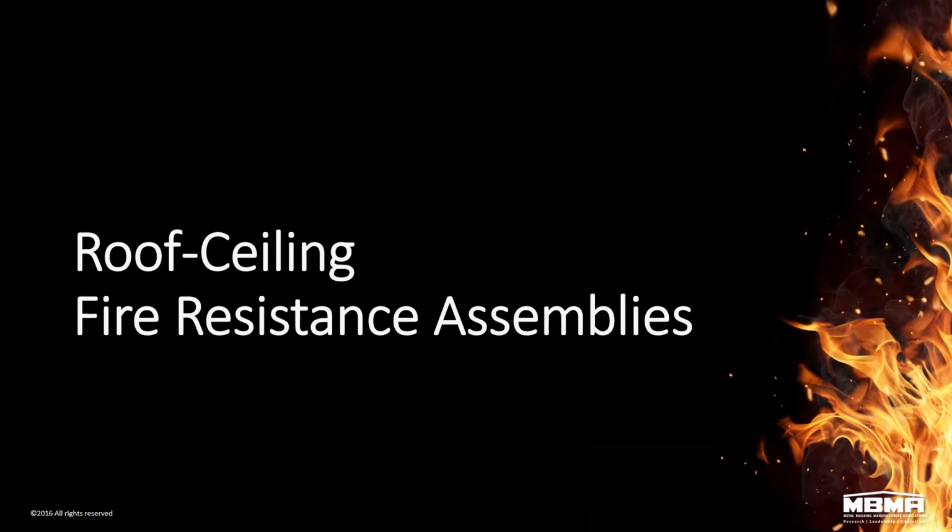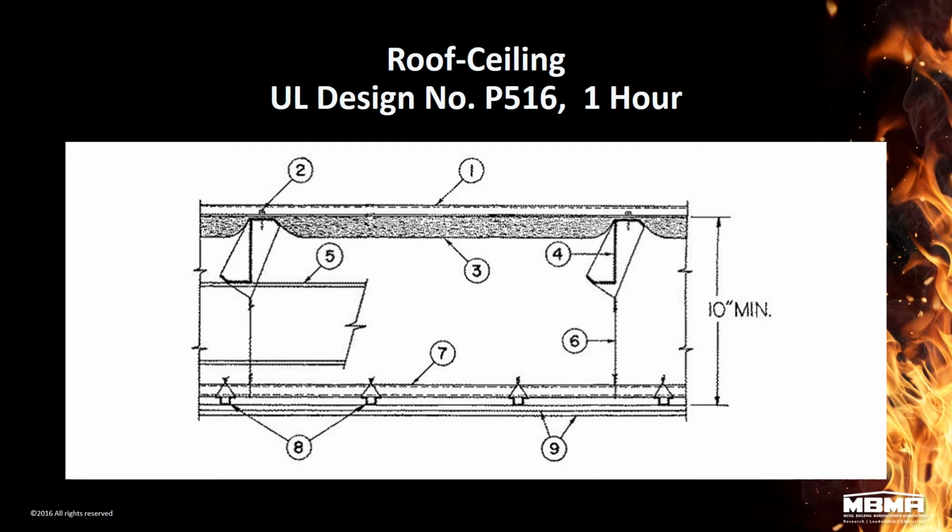Now some roof ceiling assemblies that MBMA has developed. One of these is your gypsum board ceiling, P516. This is a 1-hour assembly. Typically for metal building construction, we don't need to go any higher than 1 hour. So 1 hour is the maximum that has been developed.